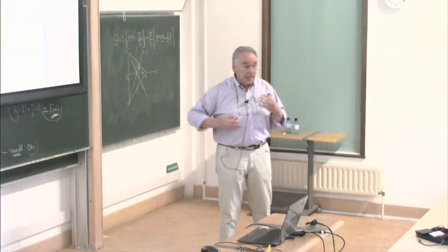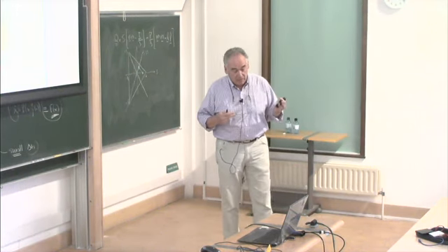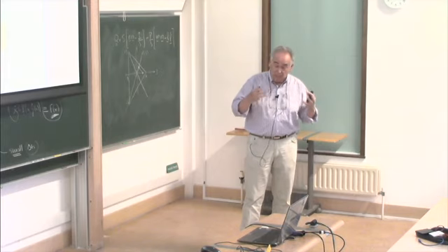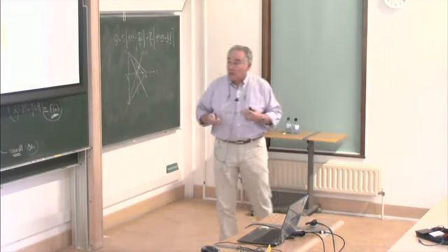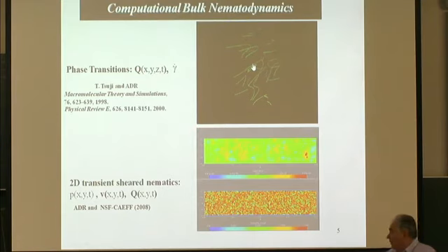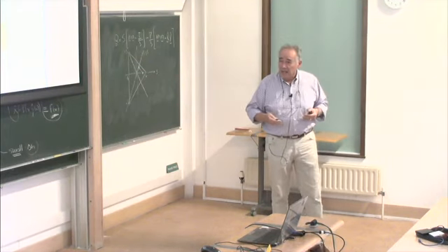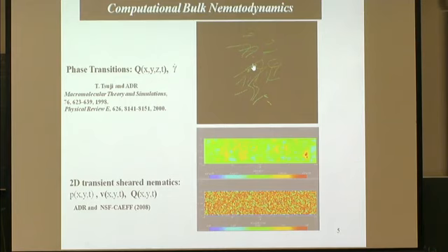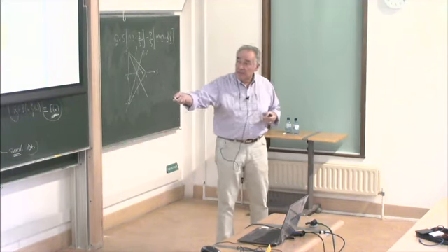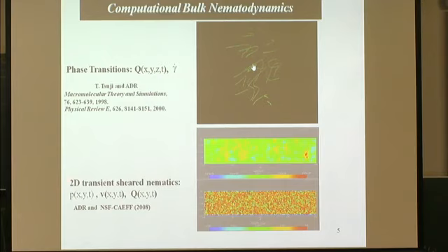And the second step, that still ongoing process, so that was simulations in the late 90s, was to start doing coupled flow problems. So here we coupled the fluid mechanics, fully coupled, with the Q tensor dynamics. So this also we worked for 10 years with 50 people, the National Science Foundation Center of Advanced Fibers and Films. So there were a lot of people involved, and one of the tasks was to come up with a solver for these nematodynamic equations that are fully coupled to the Navier-Stokes equations, and we achieved 2D transient solutions, solved for pressure, for the three velocities, and for the Q tensor.